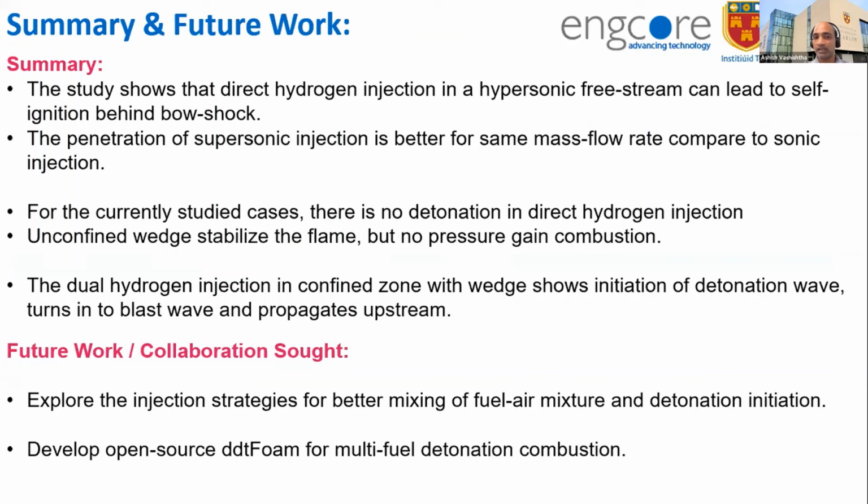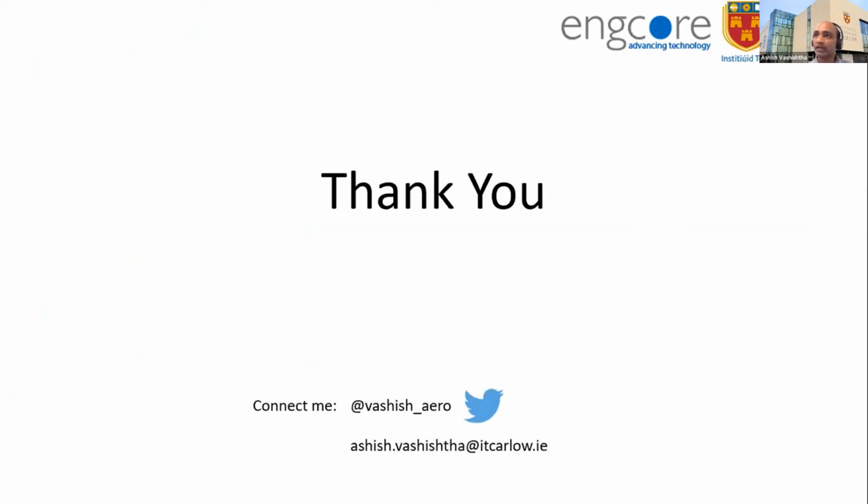So the dual injection in a confined zone with a wedge shows initiation of a detonation wave, which can turn into a blast wave and propagate upstream. And so the future work will be to explore the injection strategies for better mixing of the fuel-air mixture and detonation initiation in a non-premixed combustion system, and also to develop an open source detonation solver for multi-fuel detonation combustion. There are actually a few labs which have developed such solvers for multiple fuels, but they're not available in open source. So I'll be looking for future work in that direction.